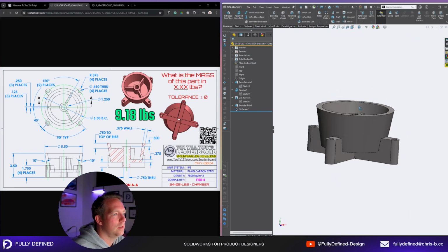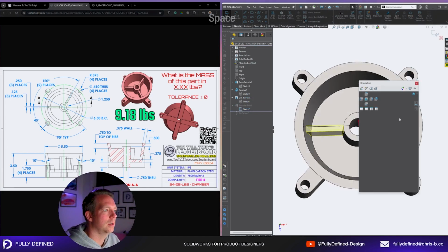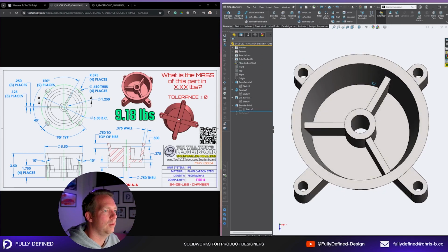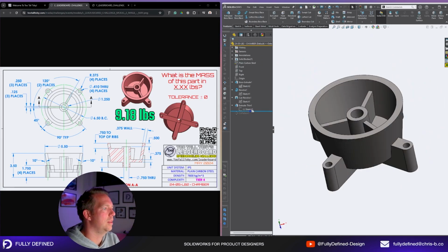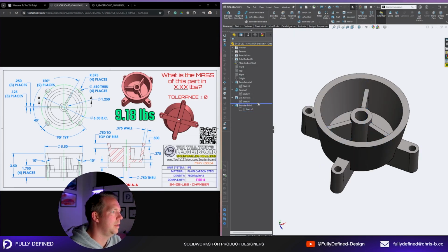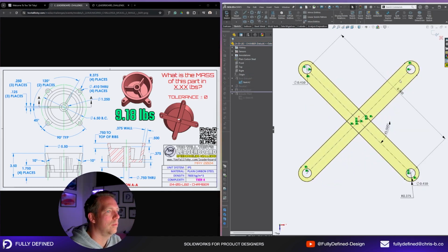All right, so first thoughts on efficiency. I'd like to be able to do this all in one hit, which you know what, I think I probably can. Just by doing 3 sketches, it should work. But I have to do the linear pattern here. It's not going to be fully defined, but it will function. That's okay. I don't mind that, and that is much quicker than doing a pattern. So that can stay. And then my others, so I've got one sketch on the bottom. This sketch here, where I'm doing one shape.